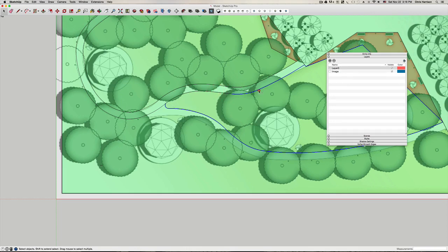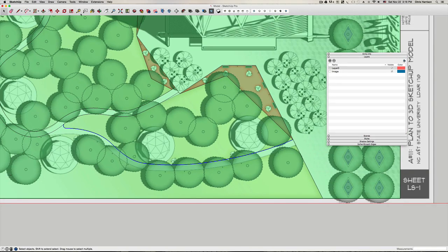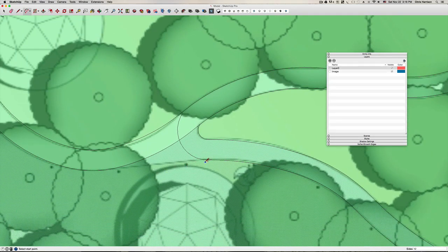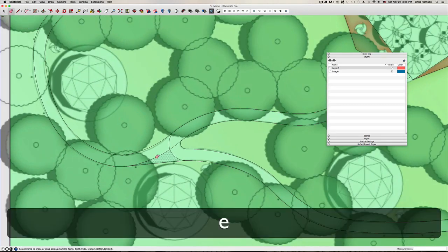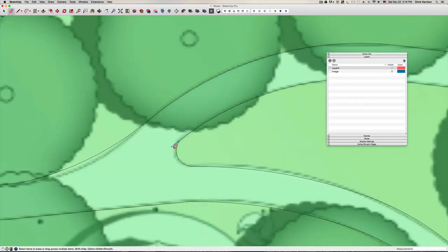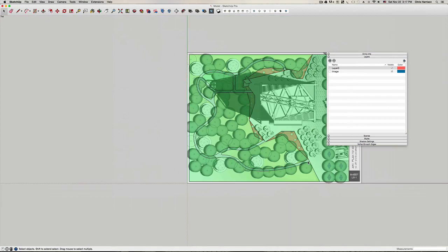Let's say principal again, just deselect the lines that I don't want so I don't have all this extraneous line work to delete afterwards. And do that, and then I'm going to use my offset tool again and come up with 6 feet. Alright. And back to that tool and click this point, trying to get something to line up. Alright, and I'm going to delete this stuff in here. Delete that. And I want to make sure this one's closed. Just come out. So now we should have a face.